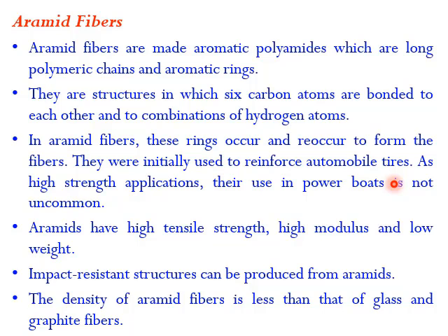So they are used in automobile tires, and in high strength applications like power boats. Aramids have high tensile strength, high modulus and low weight, so impact resistance can be produced from aramids. The density of aramid fiber is less than that of glass and graphite fibers.